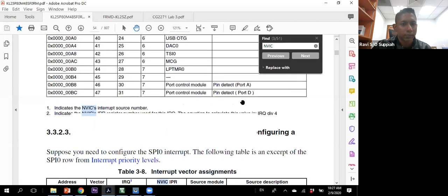By looking at that PSR register, we know that we are currently servicing the port D interrupt request. So that is the handler mode and the interrupt request that is registered in the processor at the time. Now I'm inside this IRQ handler.